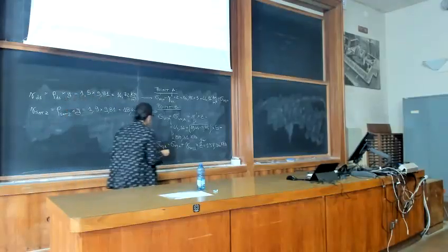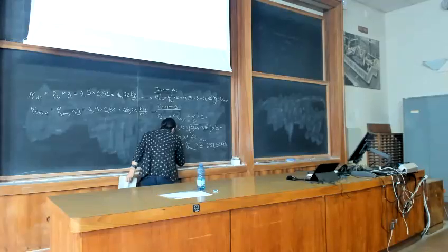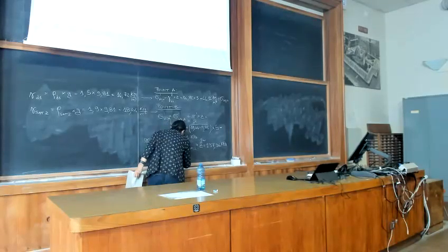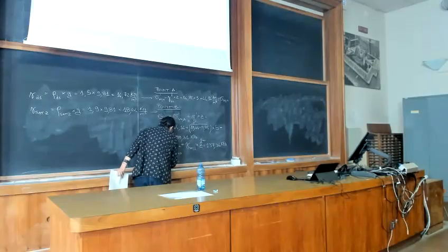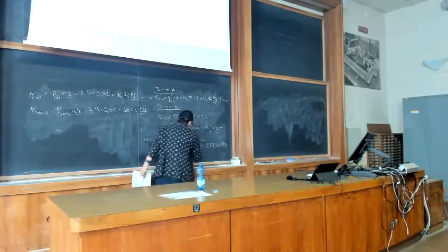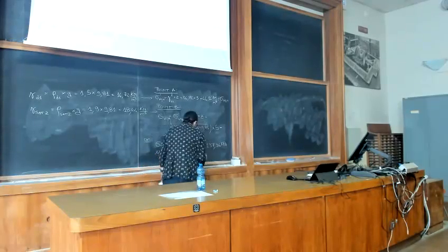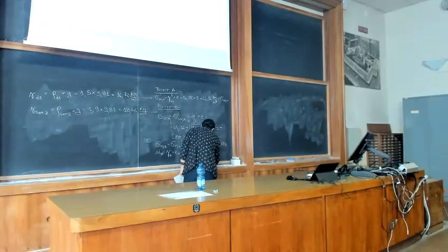So in this case you have gamma W, which multiplies delta ZW in point B. So this is U naught in point B. And you have 9.81, which multiplies 5. So you obtain 49.05 kPa.